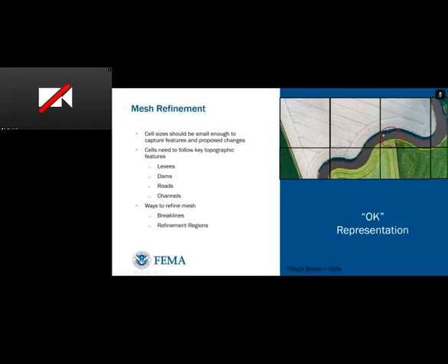So that means that our very low stream elevation against our higher overbank elevation is averaged into a single calculation. And this is okay, but a better representation would be smaller grid cells. So now within this cell, it's mostly going to be stream elevation, but we still do have some overbank elevation that's going to somewhat falsely increase the elevation within our stream.